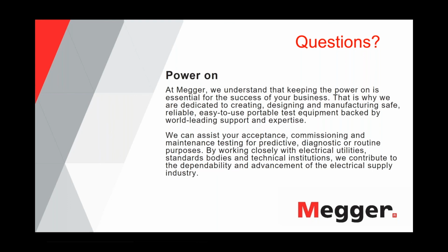And that's also the reason, because different cable manufacturers use different formulations of the copolymer and also the amount of filler they put in. That's why, in contrast to XLPE, where XLPE is, let's say, a unique compound that, regardless of the manufacturer of the finished cable, XLPE has the same properties. But on EPR, it depends very much on the manufacturer what the exact dielectric properties of the cable are. And like I said, EPR is always mineral filled.